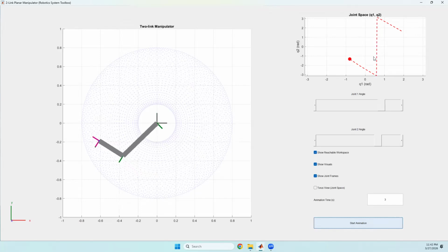and it seems like there's some discontinuity in the joint space. However, the configuration space is actually continuous. We don't have any discontinuities in it, and this is just one of the artifacts of representing the configuration space in this way, simply as a piece of paper, or R2 as a plane.